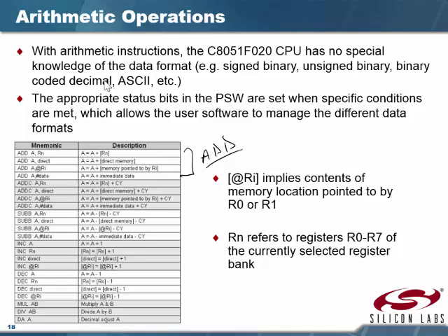The first one is using register addressing. The second one is using direct memory. The third one is using indirect. The next one is using immediate, and that's it. You got four addressing modes right there. So you can add to the accumulator 2 registers together. Now notice that the add always ends up in the accumulator. That's our main register.